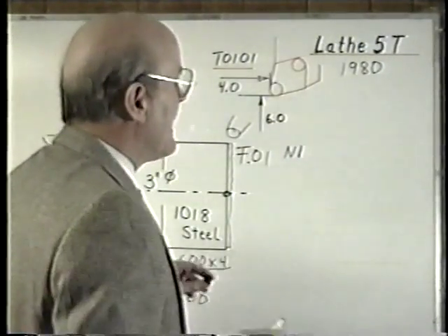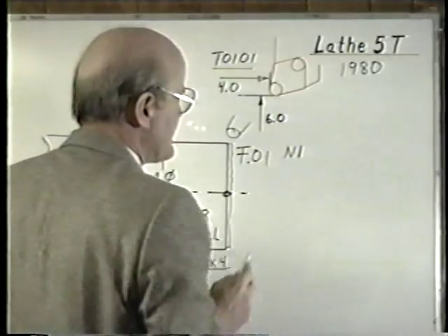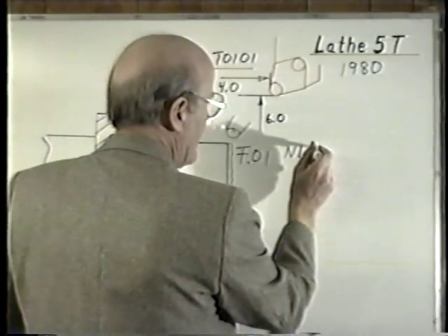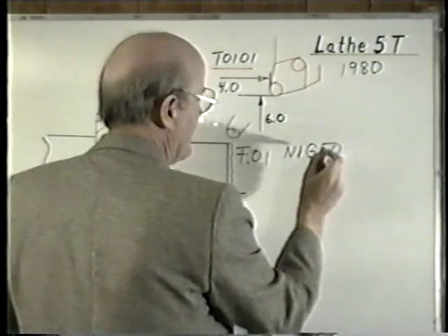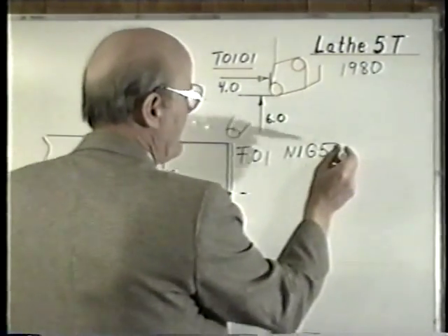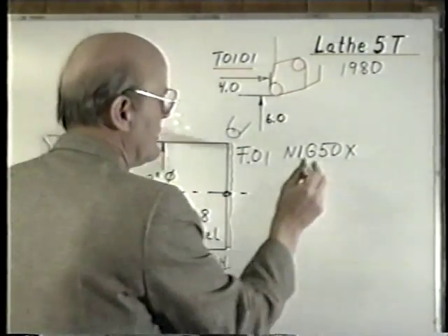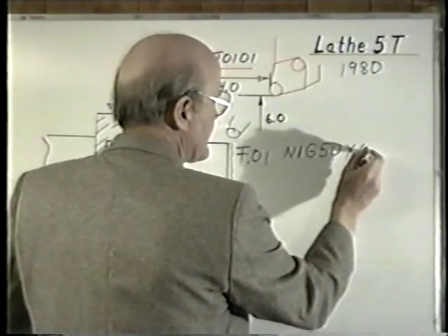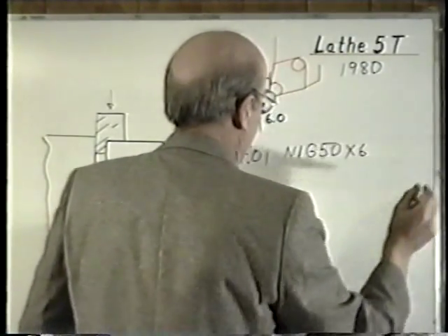this did not have a program number. We just had line numbers. We normally started with line number 1. There would be a code that would look like this. It's called G50. And the dimension following the G50 would be the dimension of where this tool is sitting. It is sitting at 6, and the number had to be written out longhand.